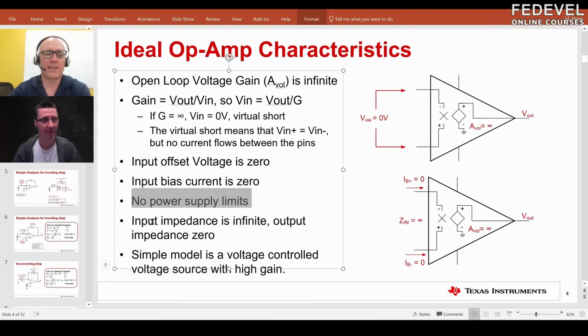When I say the gain, A-wall, is infinite, yes, gain is infinite. It means on the output there will be the voltage that is on the power supply. Well, if you were to leave it in this open loop configuration, which we'll see in a moment, which isn't really how they're normally operated, but if you put even some tiny little voltage on the input in this open loop configuration, then basically the output would hit one of the power supply rails. If the positive supply is 5, it'd go to 5. If the negative, it could go to the negative supply. So that's not how it's operated.